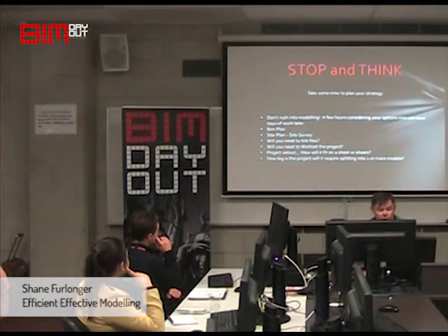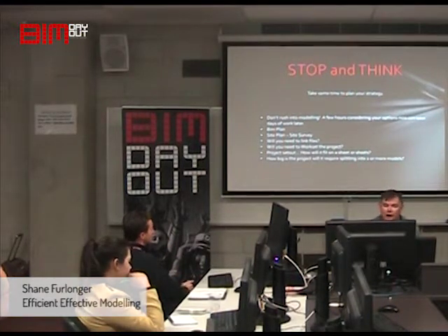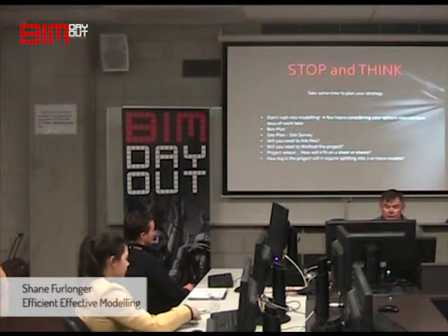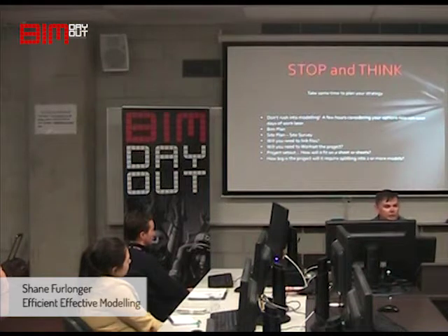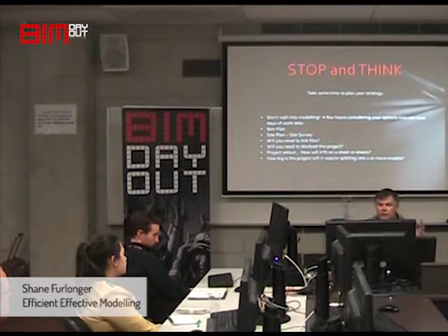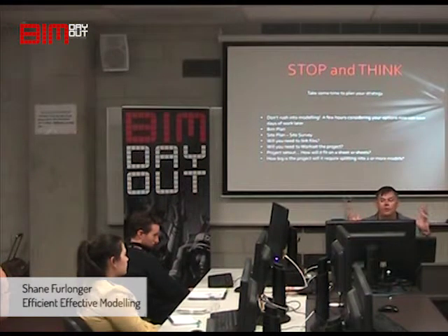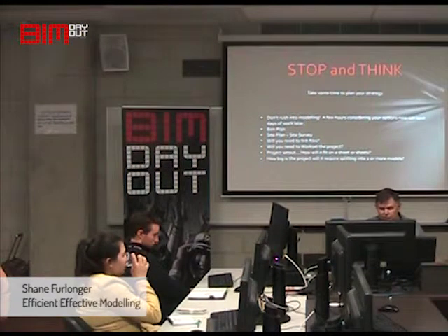So work sets, don't overdo them, just keep them to what you need, and mainly the use of them nowadays is to not load stuff into your project so that you can move easier around your project. As I said before, project set out, how are you going to fit it on the sheets, depending on how big your project is? You need to think about that because it's the orientation of your building, Project North, as it is in Revit, and how you originally set it up.